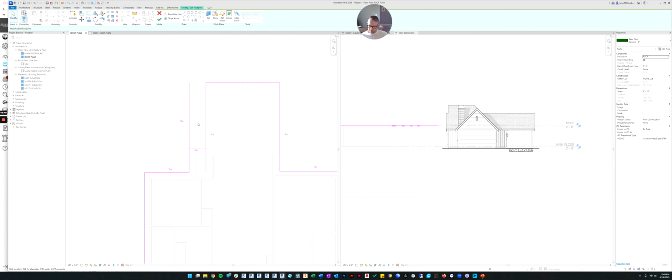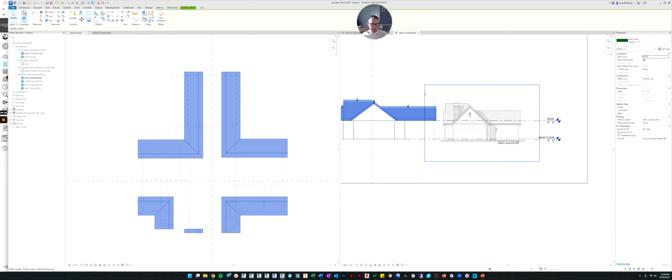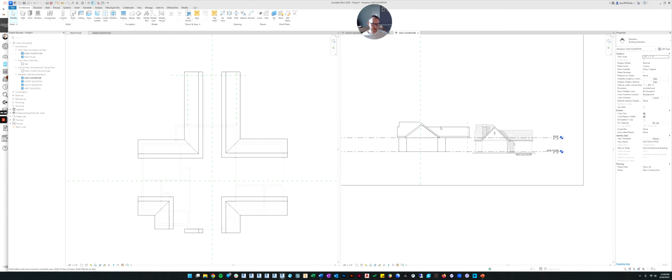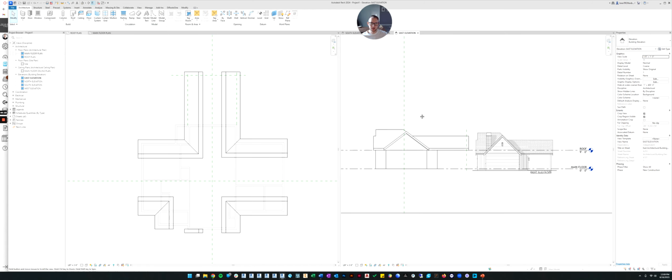So now let's trim these the way we want them. And this actually isn't going to quite do what we want it to do on the back. So I'm actually going to trim it like this. And I'm going to delete these 2 lines. So I'm going to select them and I'll just hit the delete key. And we'll see what that does. That should be roughly correct. So let's hit finish. And now you can see from the side we look much more in alignment.